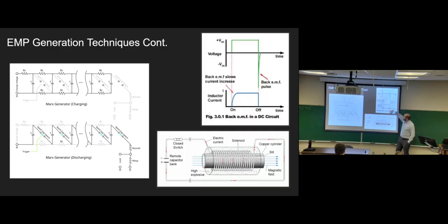It says negative, but it's still drastically larger in magnitude than the actual DC voltage would have been if you were talking merely resistance. And the reason for that is, again, it resists a change. So while this reaches a very high peak voltage, it is not cheating thermodynamics. Energy is not coming out of nowhere. It has very little current behind it. So it's a very large static voltage, but it's not a high current, not a lot of energy there.